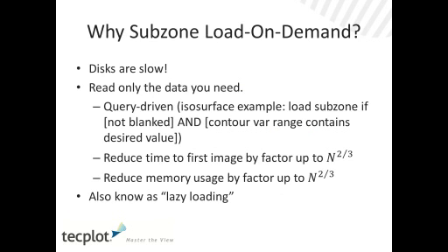So this changes how the required time to the image you want scales as your problem size increases, and reduces the time to first image, or your image if you're loading a layout, by a factor of up to n to the 2/3, where n is typically the number of cells in your solution. There's also a corresponding reduction in the amount of memory that you need to load that layout. Another term for this technology is lazy loading.